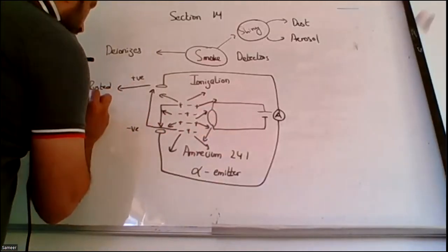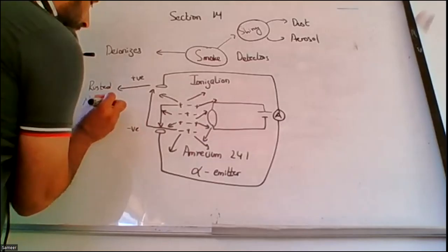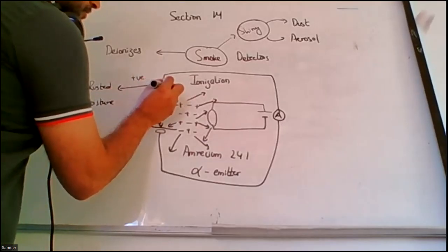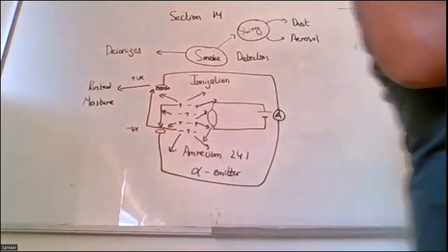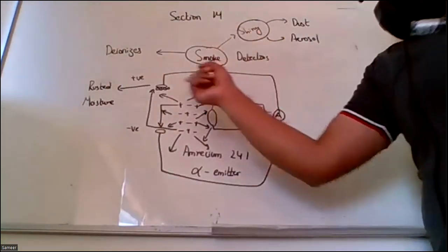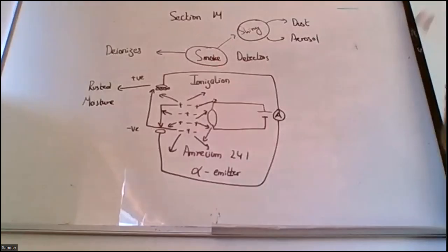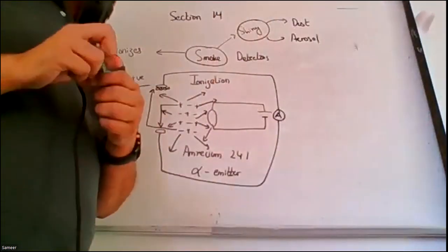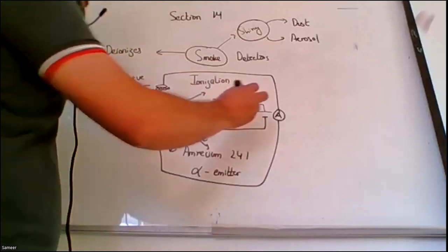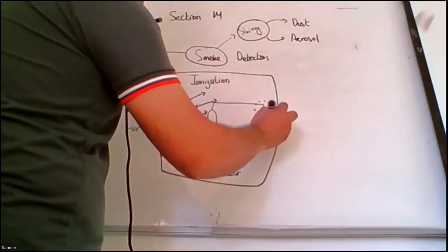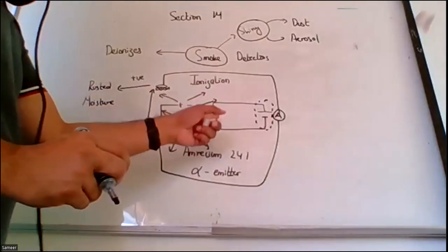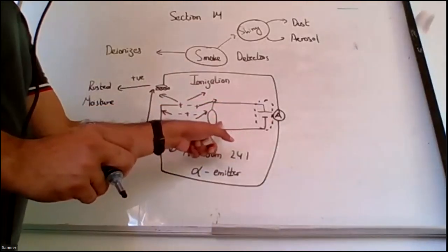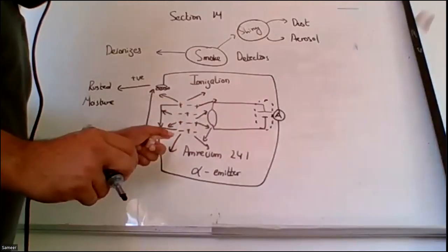Similarly, if there is any type of moisture accumulation, droplets, that will also give discontinuity in the electric current. Any accumulation of anything on the charge plate. Then if your radioactive element is not giving charged ions, in other words if there is any problem with your batteries or power source, the radioactive element will not give ions.